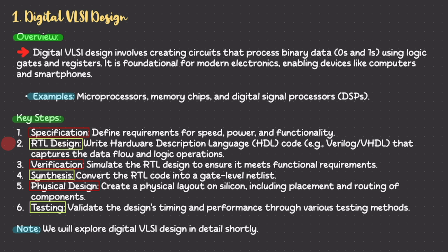The second one is RTL design. Here we are creating the design using a hardware description language. What is a hardware description language? I'm going to take another lecture on that in an upcoming video. For now, just understand that we have hardware description languages, for example Verilog or VHDL, which we use to describe the data flow and the logic of our chip.